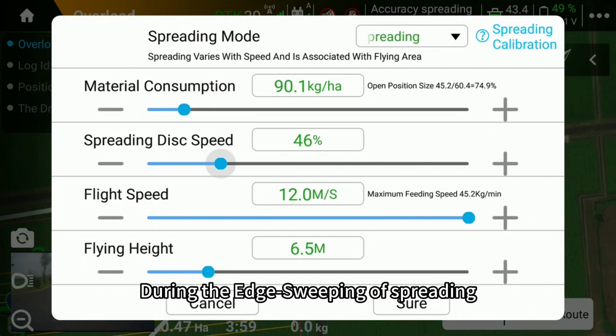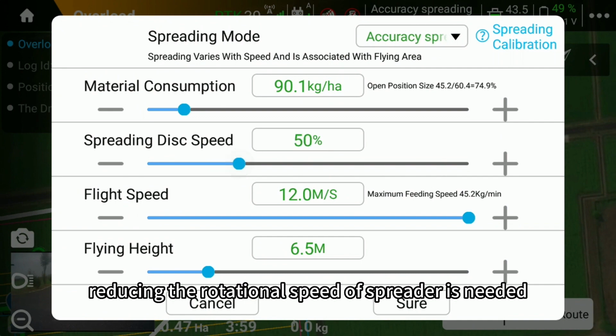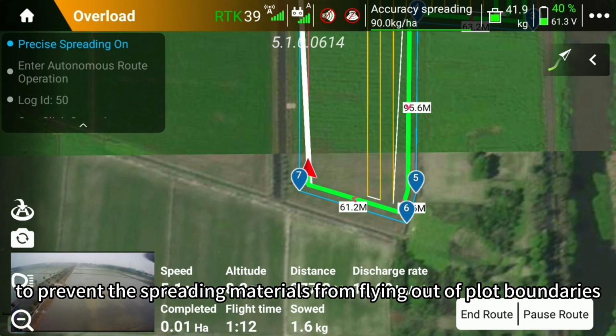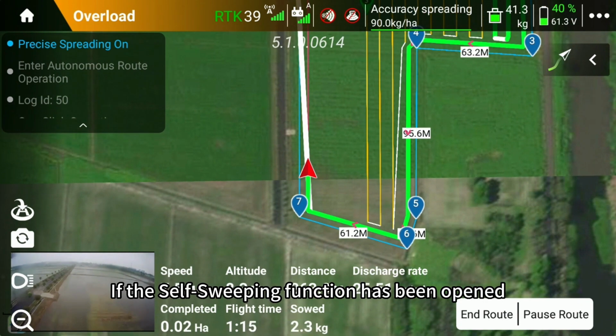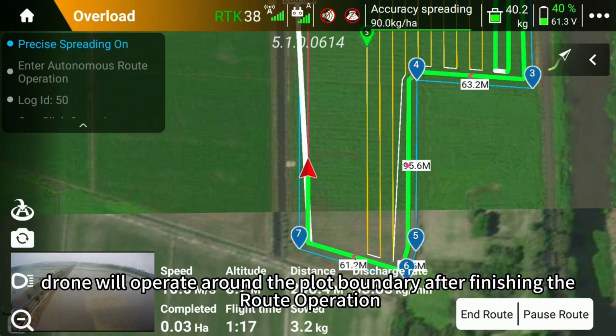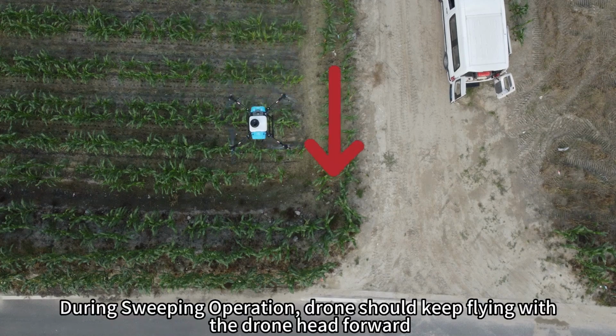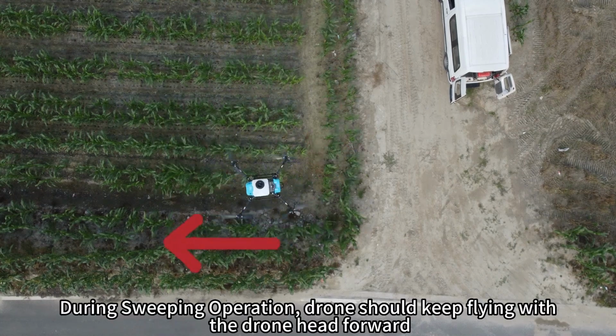During the edge sweeping of spreading, reducing the rotational speed of the spreader is needed to prevent the spreading materials from flying out of plot boundaries. If the self-sweeping function has been opened, the drone will operate around the plot boundary after finishing the route operation. During sweeping operation, the drone should keep flying with the drone head forward.